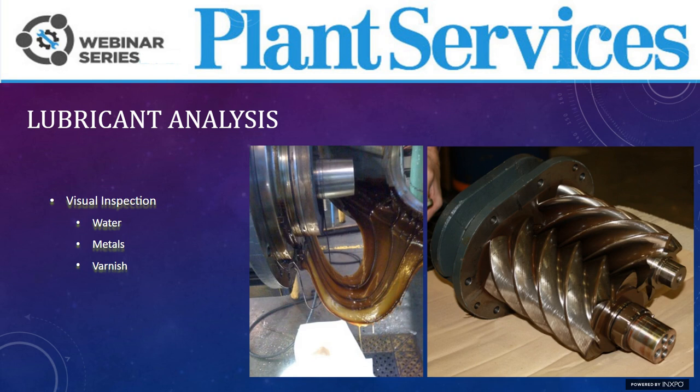Items to look for when you're taking a sample would be water, metals, and varnish. The pictures here show instances where failures have occurred. You won't be able to see this kind of definition per se with just a sample, but with these images you're going to see the effects. Without proper lubrication, there's going to be failures. The point of the oil sample would be to help determine these issues prior to a failure.